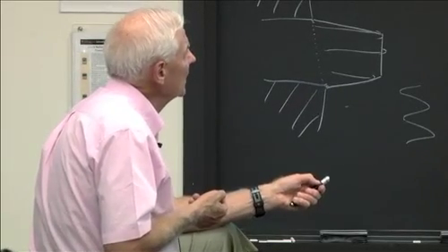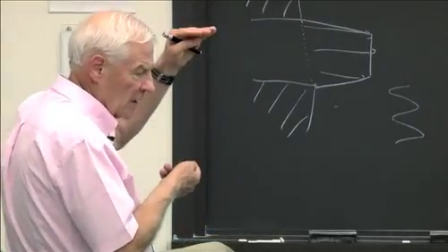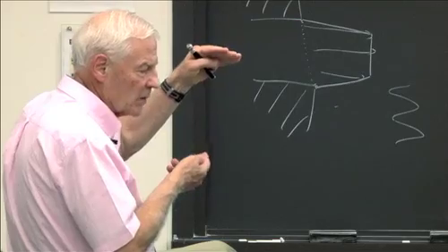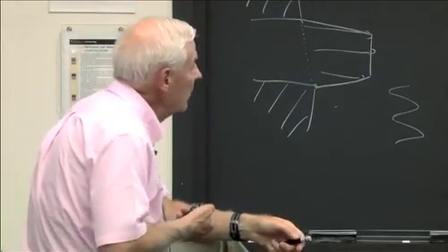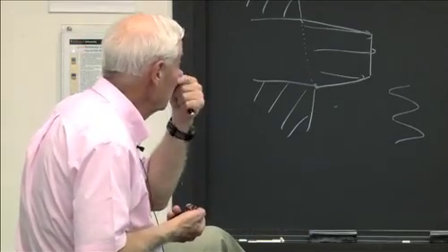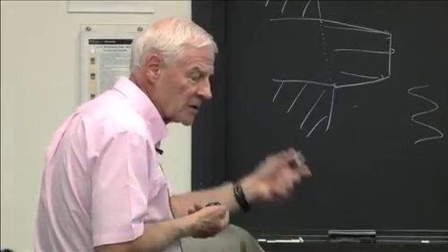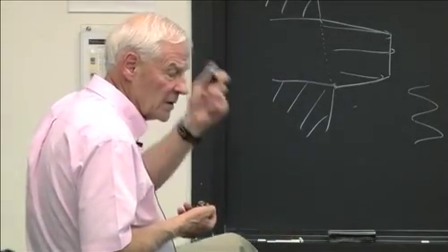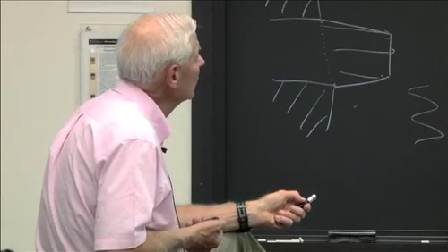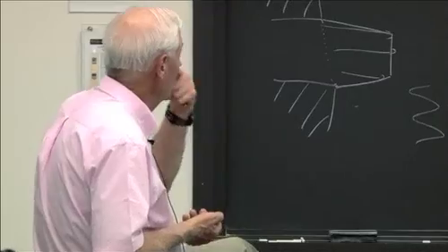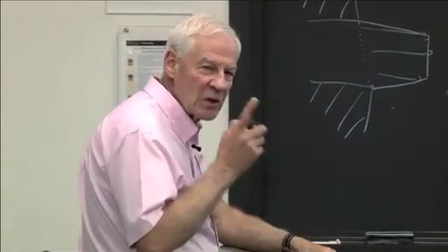So I worked on this and I realized we could measure absorption at 760 nanometers due to what's called the atmospheric A band, which is a weak transition, but it's strong enough that there's 2% absorption per meter. And we could, by combining velocimetry with Doppler effect and by measuring the density of oxygen and using the known mole fraction of oxygen, get the mass flow of air into this engine. And it worked really, really well. We did that in 1989, got an award for it. And then, this laser was room temperature. And the first laser I bought was $12.